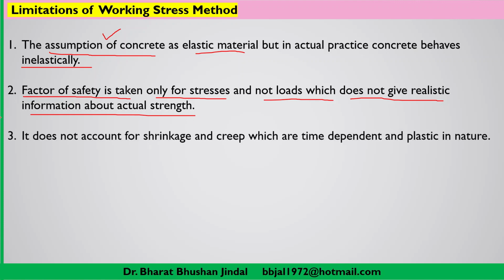The third limitation is that in the working stress method we don't discuss anything about shrinkage and creep. So far we have discussed the working stress method, and it does not clearly indicate what provisions we have taken for concrete when it is subjected to loading and when shrinkage and creep stresses develop. And we have discussed that shrinkage and creep stresses are also time dependent and plastic in nature. So here the working stress method is silent about the stresses which may develop due to shrinkage and creep.